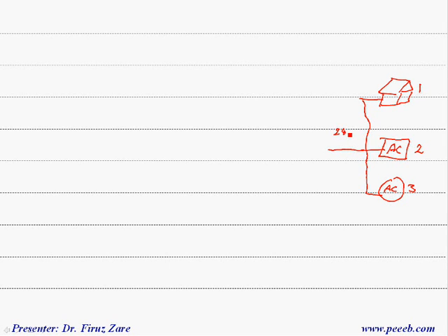So finally, this is the power system. That means for these three different types of loads, load 1, 2, and 3, these are connected to this AC system, which is basically 240 volts and 50 hertz, through this output filter, and this filter is basically connected to a high power DC to AC, and the voltage at this terminal is, for example, 400 volts.